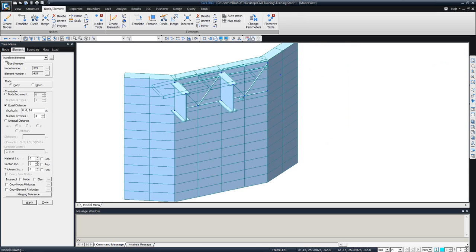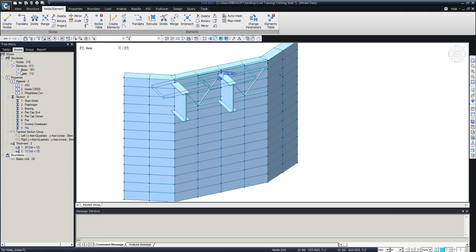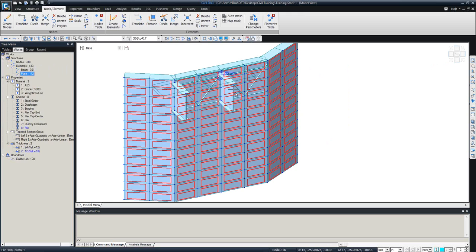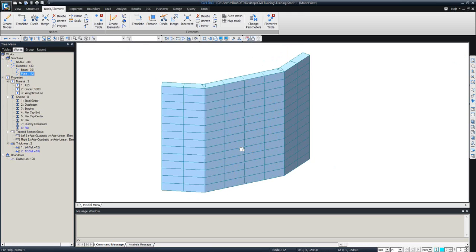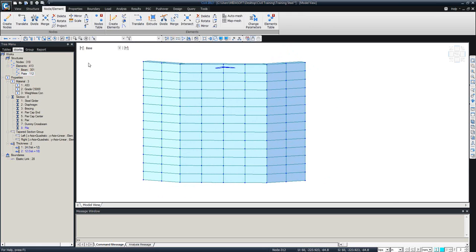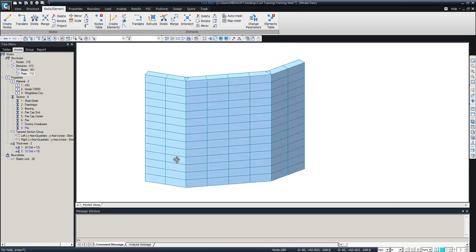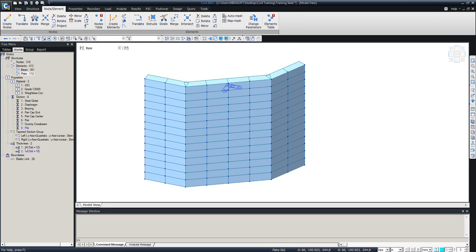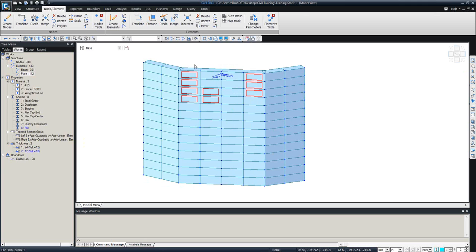How to do that? All right, so I have many elements here. To get rid of those, what you can do, you can just simply double click on the plates. All the plates are activated, and then you can say activate. So now I'm not seeing those elements. And how to change this one? I want to change this with the smaller, thinner elements that I have here. So just simply select these guys, and drag it from here and then drop it here.